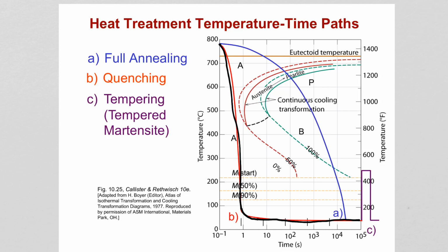Tempering means, remember what tempered martensite is. So you heat up the material to higher temperatures, in this case somewhere between 200 and 300. There you keep it for some time, and then when you cool it back to room temperature, so we heat it up, keep it, and then cool it back to room temperature, and then keep it at that temperature. We are seeing some of those martensite might turn into bainite, some cementite together with alpha ferrite.